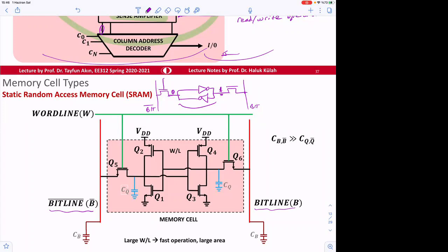In the past, we have seen that we can do that with SR flip-flops. But here, the data is going to be written from a line. This line is touching this bit cell, or the upper bit cell, or this bit cell. Each of them is a bit cell. So how do we decide which one to access? We give a signal to here, the select signal. So the word line determines which one we will be accessing.